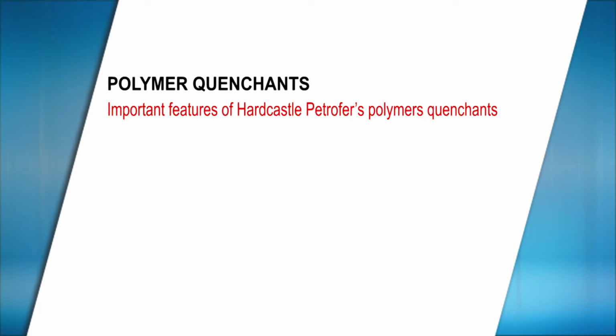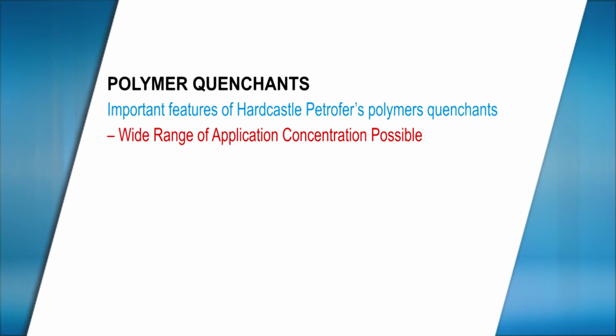Hardcastle Petrofer has rich experience of formulating and manufacturing polymer quenchants. The wide range of polymer quenchants available provides the users the choice of options to suit their performance requirements. These polymer quenchants can be used in a wide range of concentrations in water. This property provides the users with the flexibility to use the same polymer for quenching of a variety of steel grades and also for use in induction hardening as well as tank quenching applications.